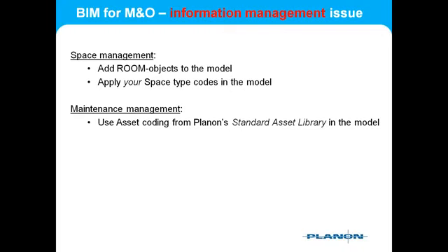For space and workplace management, it's useful to add so-called room objects to your model. By the way, a room object is a term that comes from Revit, but other modeling tools also have similar options. These room objects contain data that can and will be used by solutions like Planon to set up space management. If you don't have these objects in your model, it contains only floors, walls, ceilings, etc., but no spaces itself.